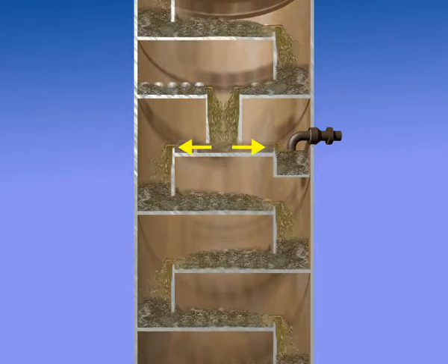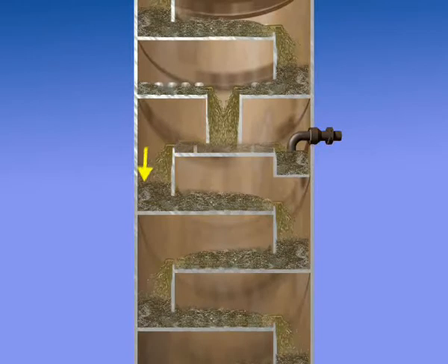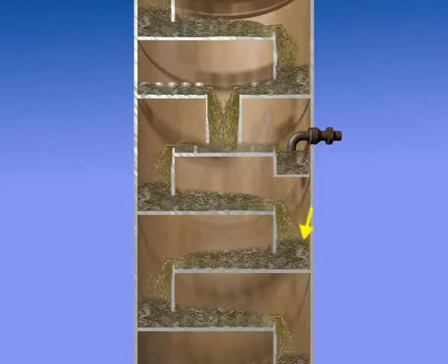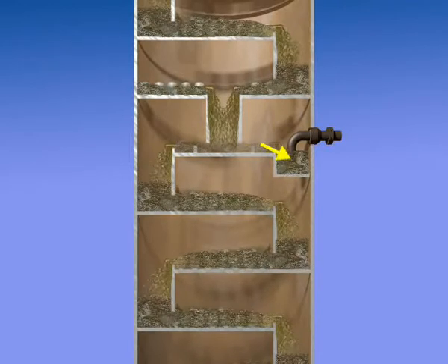On both sides of the downcomers on the tray below, a weir is present to maintain the appropriate liquid level. The left side of this tray continues the liquid downflow. On the right-hand side, the tray level drops to create a larger holdup area from which the liquid can be pumped out to the appropriate equipment.